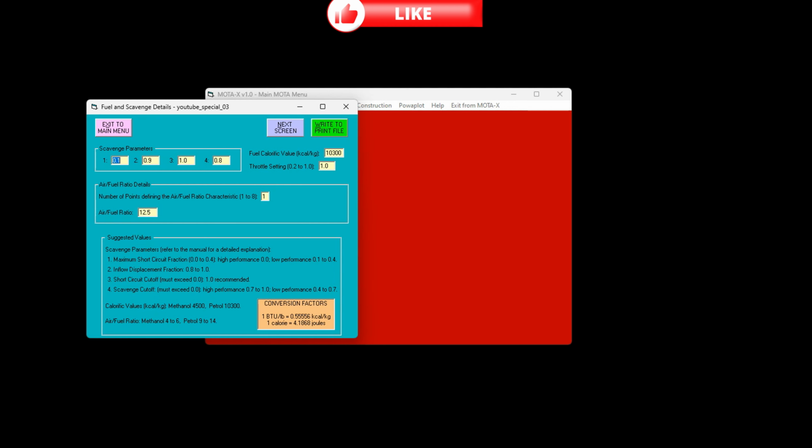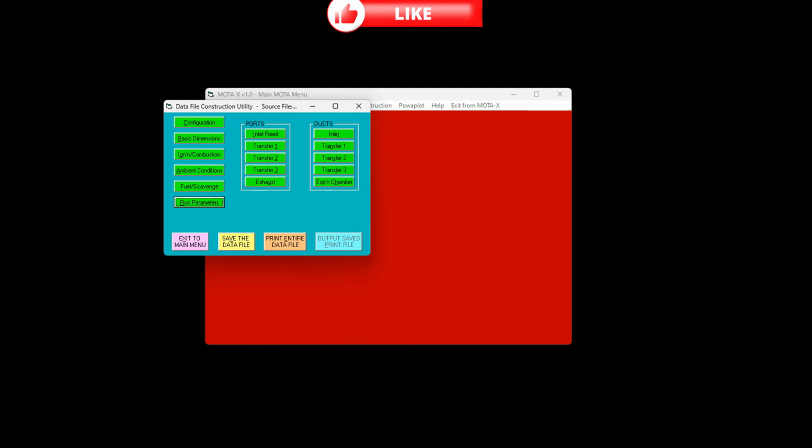If having a power jet, you can set a curve here, like 8 points at different RPM points. And then the power jet adds fuel at the maximum airspeed in the throttle, which is maximum torque, it can enrich the engine, and by that making it leaner at the top. Well, I'm not using that now because I want to compare it.